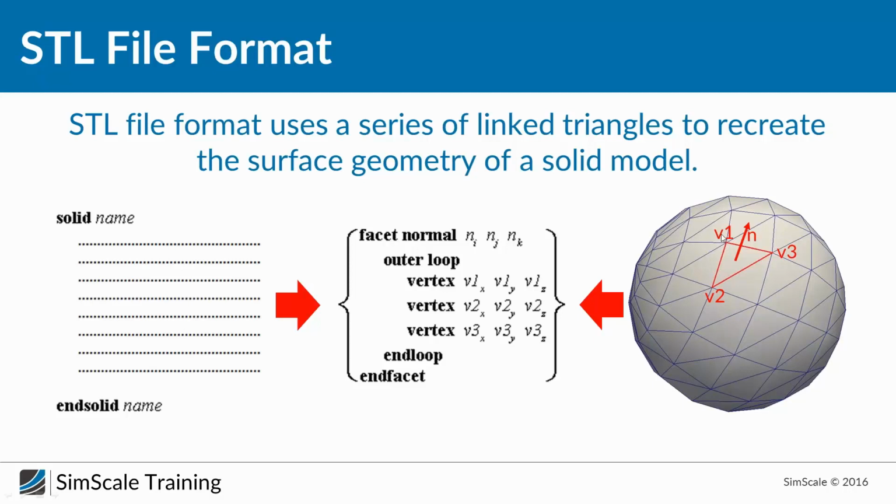Like you can see here, V means vertex, and we have 3 vertices to represent a triangle. And of course, if you have a quadratic representation, you will have 4. We also need the 3 components in space of every vertex, so for 1, 2, and 3. And we also need a normal that will represent the direction of the surface.